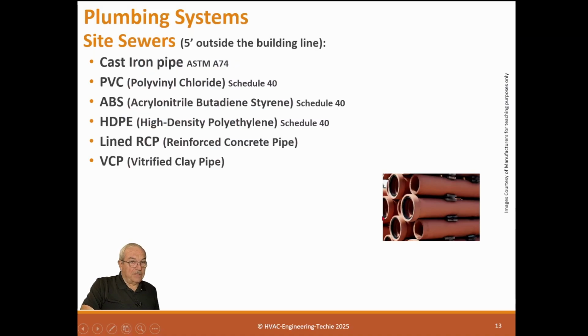You can see it has rubber gaskets, and you plug them together. Now, originally, bell and spigot didn't have rubber gaskets because they didn't have the rubber. They actually used oakum and lead. In a sewer line, like you see, it would just be oakum, which is kind of a wood fibrous material, and they would pound it like a rope into the joint, and that would make the seal, and it would stay there because it's underground. If you were above ground or using cast iron, they would put oakum in and pour lead around it to seal the opening. So those have been around a long time.